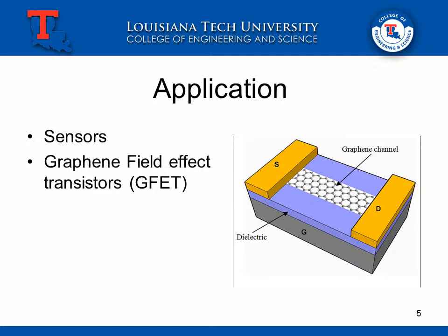Graphene used in a transistor will have an electron energy increment when negative bias is applied to the gate, and there will be a decrease in electron energy when positive bias is applied to the gate. In the case of holes, they are transported in an ambipolar graphene when the Fermi level is below the charge neutrality point, which is also known as the Dirac point, whereas in the case of electron transport, the Fermi level needs to be greater than the charge neutrality point or the Dirac point.